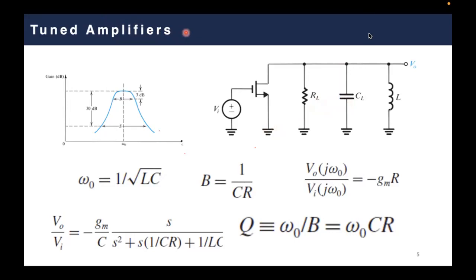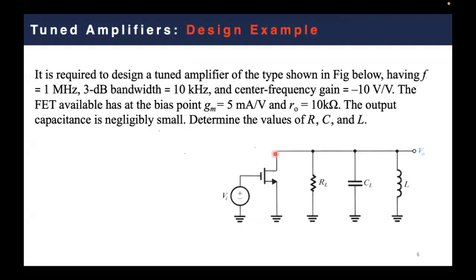Generally, you have this parasitic resistance. As I just mentioned, the resistance between the drain and the source will appear here as an added resistance to the system. So we can draw it here like that, for example. That basically means you are going to change the equivalent resistance of your circuit. Instead of having only CL, you will have CL parallel to the C parasitic. Let's call it CP, for example, or CDS or whatever.